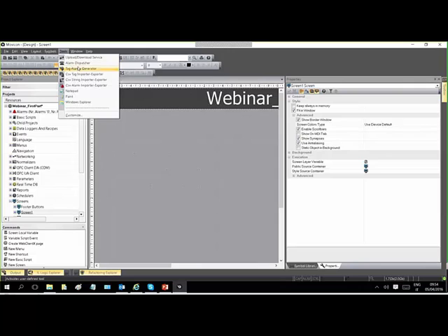Then, a few words about the dongle and the license. Movicon works in IO bytes in use, not in tags. It counts only the IO bytes of the variables that are in use by the resources: the screens, the data logger, the alarms, and the scripts. Here you know what your peak is, so you can size your license. Here you can check if your dongle is properly detected and which features are enabled.